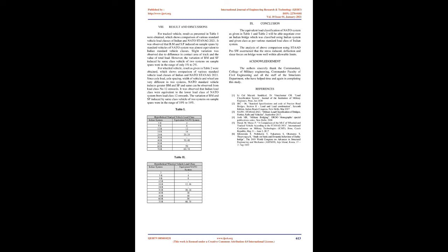Therefore, in the final comparison table, the load classes of the STANAG system which had the same SF and BM values or below that of SF and BM produced by Indian vehicle classes were placed together under the same category of class. By doing so, we obtain the equivalent class of NATO standard vehicles to that of Indian standard vehicles. The analysis was carried out for both wheeled and tracked vehicles.